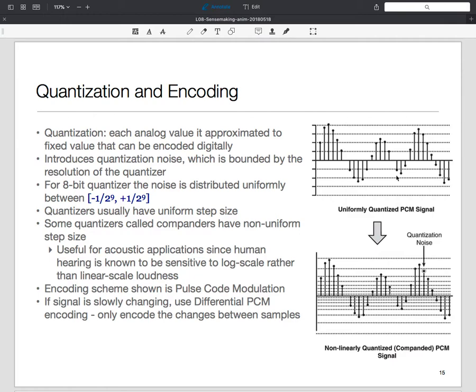So there is a spatial frequency, and the same concepts of Nyquist rate now apply in 2 dimensions. If the frequency content of the light field in the room was relatively smooth, that is low frequency, then I don't have to sample that highly. On the other hand, where there are lots of regions of shadows, the frequency content is high, so perhaps I would need a denser deployment of sensors. The same concept carries over in these other dimensions also.